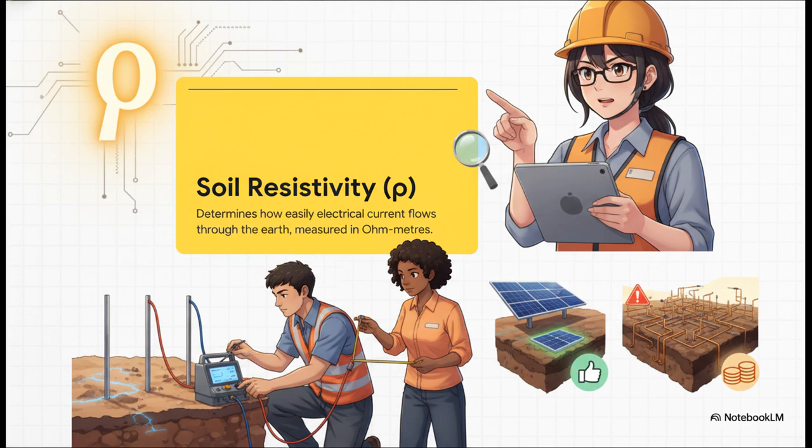Do not just pull a generic number off Google, because low resistivity makes earthing incredibly easy. But high resistivity, that requires massive, expensive interventions. You have to go out to the physical site and measure it using the Wenner 4-point method. Your entire mathematical model rests entirely on the accuracy of this one field test.